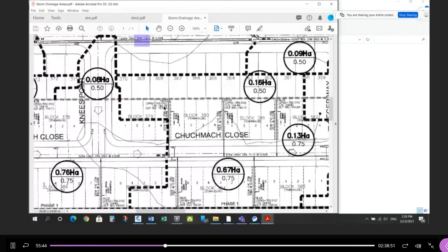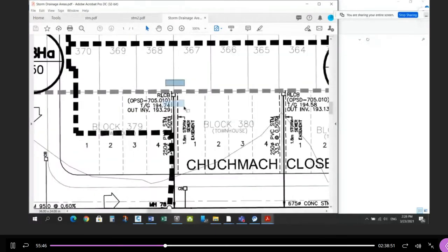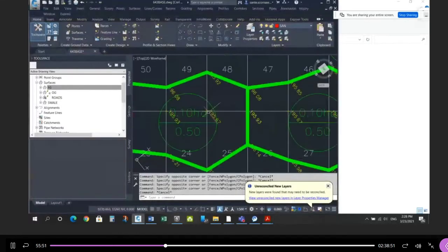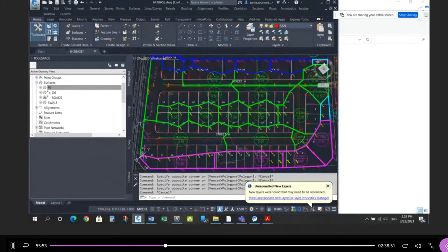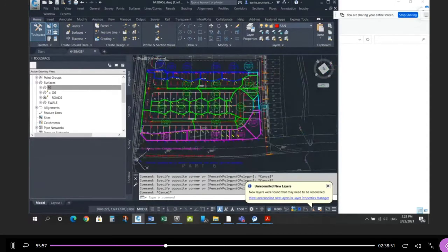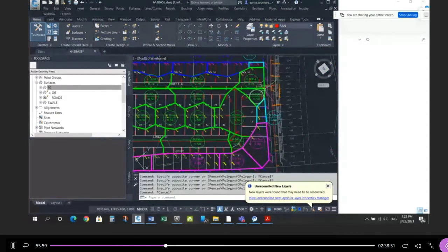Okay? So now you know whether you should put it on this side or this side. So in our case, if we go back to the drawing, we know that these pipes are higher than these two pipes. How do I know that? Remember, this is the outflow. It's going to come up to here, and then from here I'm going to go uphill to here. So now this corner is higher than this elevation.